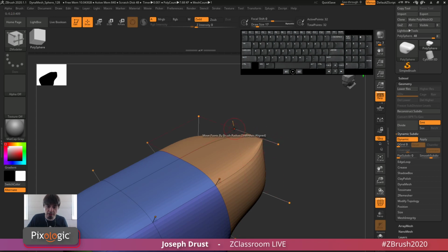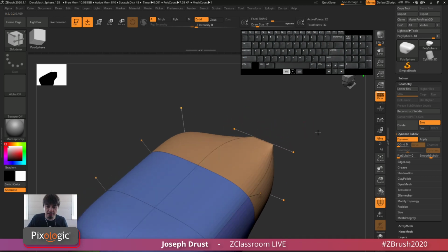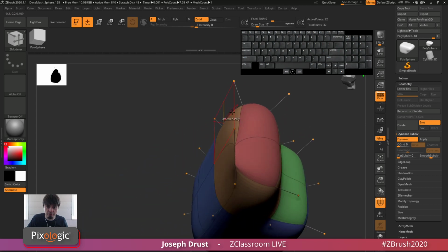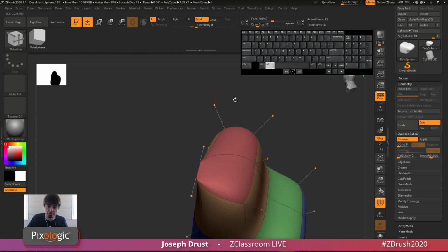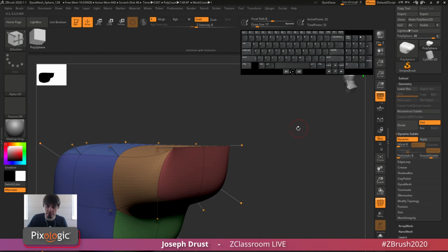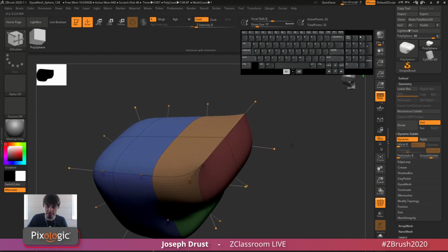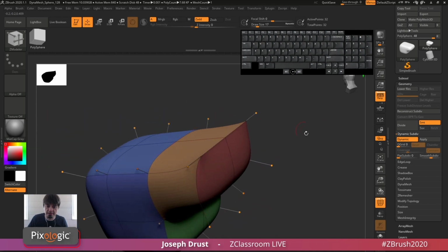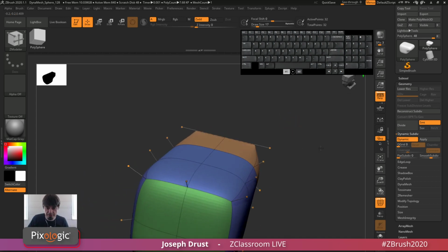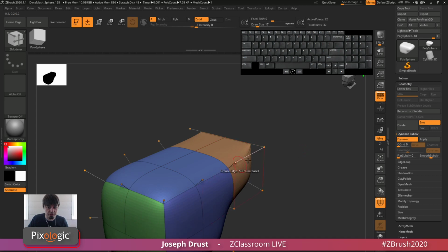And these little areas right here are going to represent what your low resolution version looks like. So this is the point that's on the low one, and it's taken that edge and creased it. Now this doesn't look like all that great yet, but let's go and add a crease to the other side too. So I'm gonna come over here, let me rotate around here. I'm gonna add a crease right there. And now I've got those both edges creased, and you see now I've got this. So it's coming through and it's now taking that edge and making it hard. Now the rest of the model isn't creased, so this is still nice and smooth.